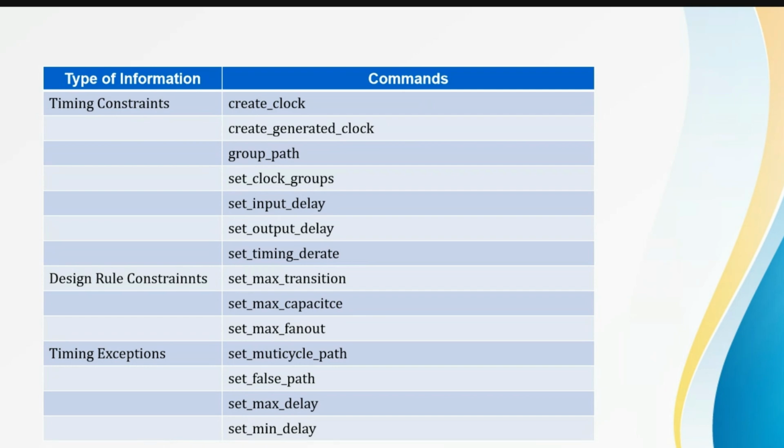How will you set the false path, multi-cycle path, half cycle path, max delay, min delay, in setup time, hold time? All of these will be defined with the help of the commands, and definitely they will ask these in the interview. So please be aware of the commands.